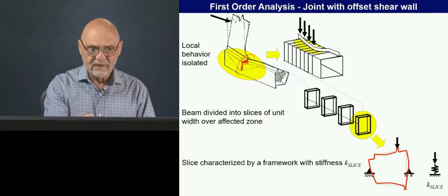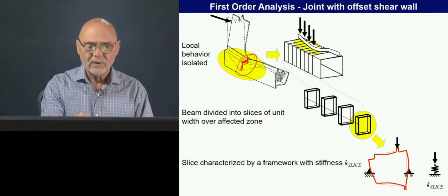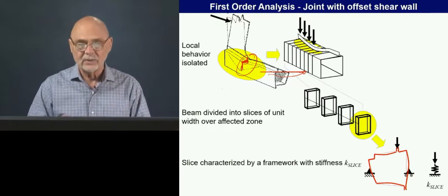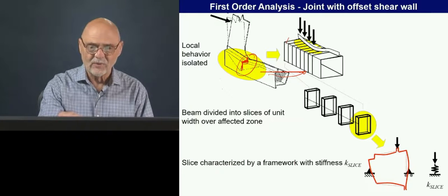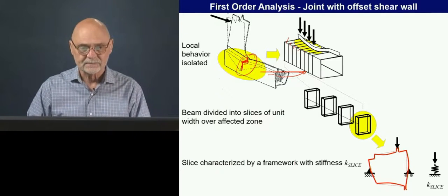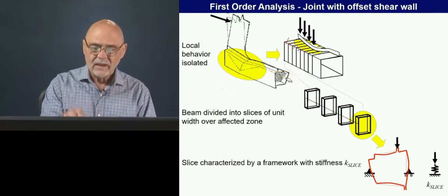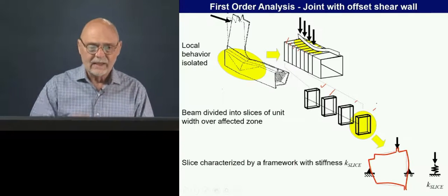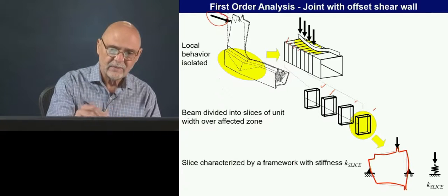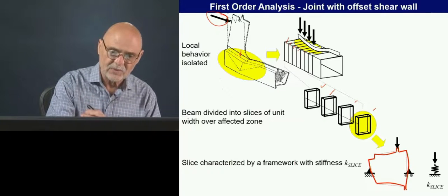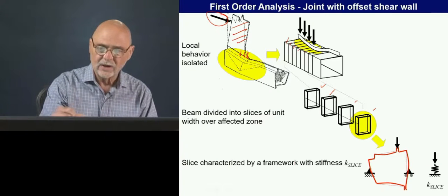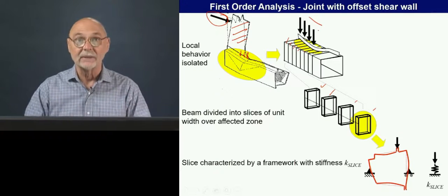We know we're going to get a lot of deformation there. So what we're going to do is view the rocker as a loaf of bread, and we're slicing the loaf of bread up into little pieces here. So that's here, here, and here, and here. As we load this, there are going to be loads applied by this hinge pillar surface along these little slices of bread.